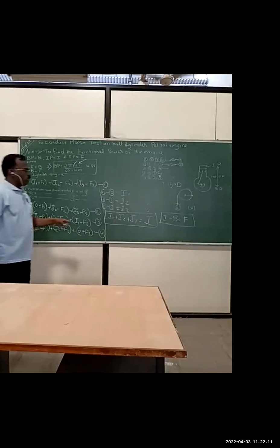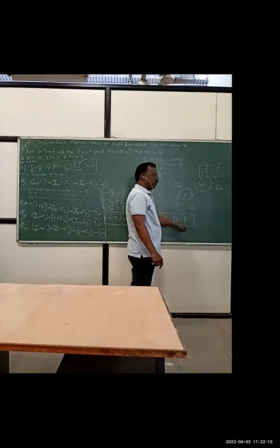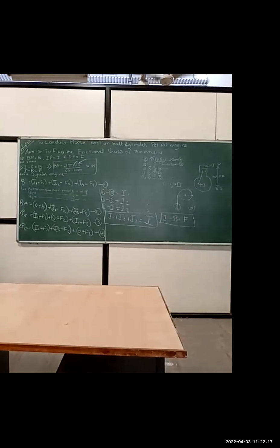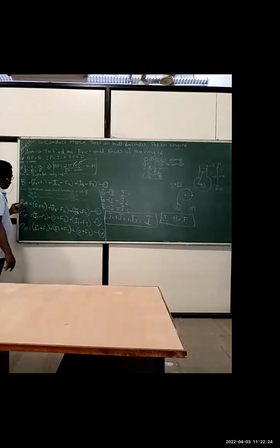Okay. So in order to find out the frictional power of the engine, see, there is no direct method of finding it. We cannot find out actually how much power is lost in the system. So we have gone indirectly. We have made arrangements for cutting cylinder number 1, 2, 3. So now when we cut cylinder number 1, whatever we are getting is I1.